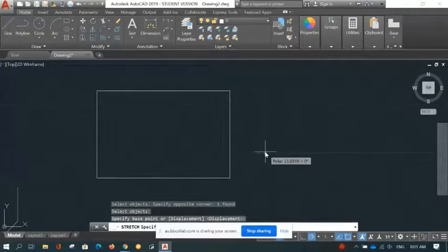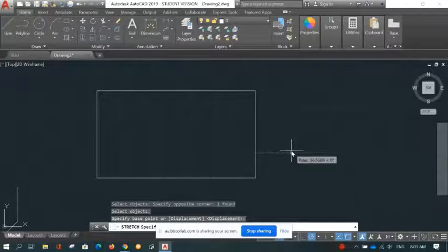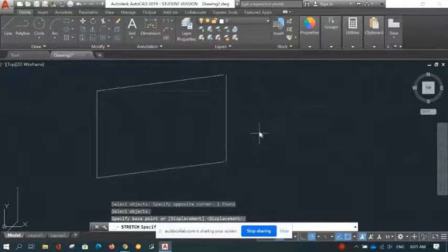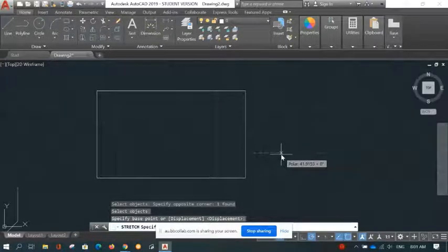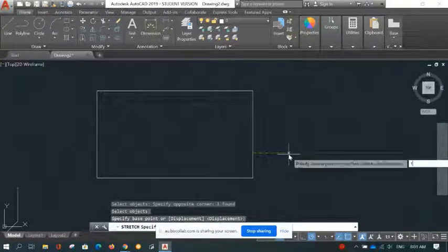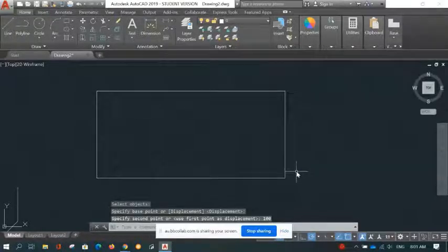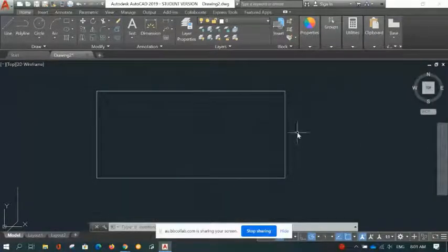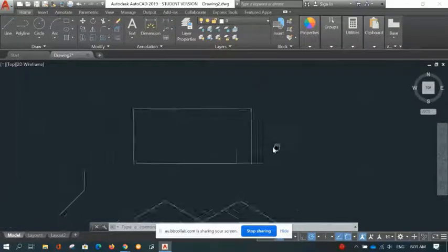Let's say you need a precision drag. So what you have to do, just select the line towards the direction you need and press F, and key in the distance. The example here, 100, and press spacebar. In that case, the shape here will be stretched to 100 mm.